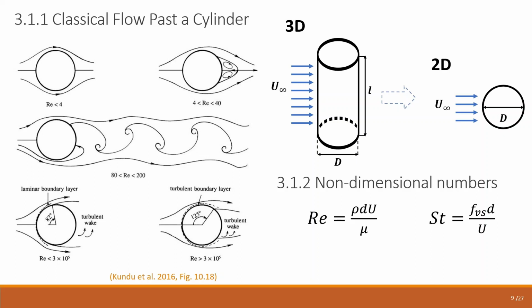Furthermore, to aid in the investigation of the system, the mooring cable can be approximated as a cylinder. Assuming that the flow is uniform throughout the length of the mooring line, and the density throughout the body of water is constant, the 3D cylinder can have a 2D approximation. This is an appropriate approximation given the well-mixed layer of the ocean is usually much larger than the length scale of the mooring line.